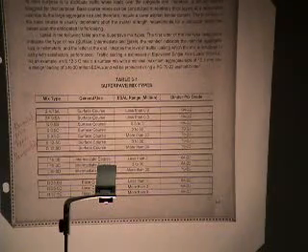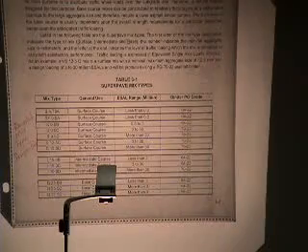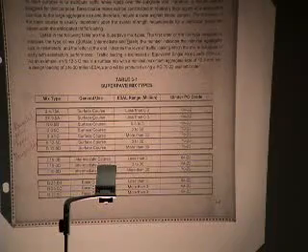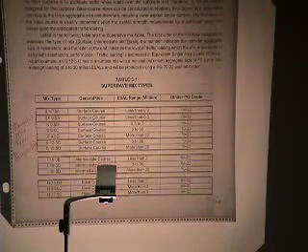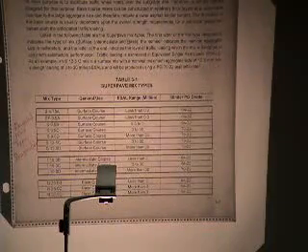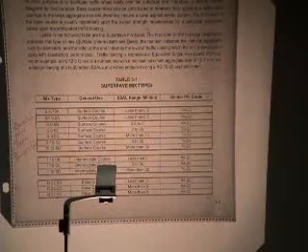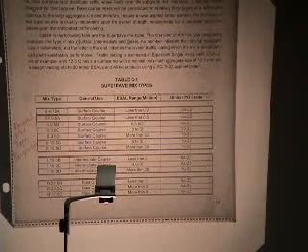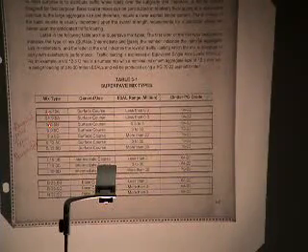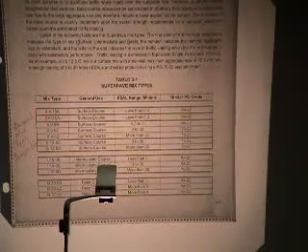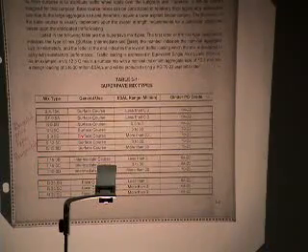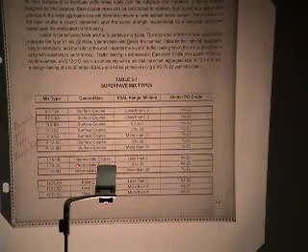Those are the upper layers, obviously, of the pavement structure. Down below that, we have intermediate mixes. These are somewhat coarser mixes than the surface in general. And then on the bottom, if you have all three layers, you would have base course mixes. So we have surface, intermediate, and base. If you look at the mix types, you'll note that they're always designated with a letter followed by a number, followed by another letter. That first letter in the mix type designation refers to whether it's a surface, intermediate, or base mix.